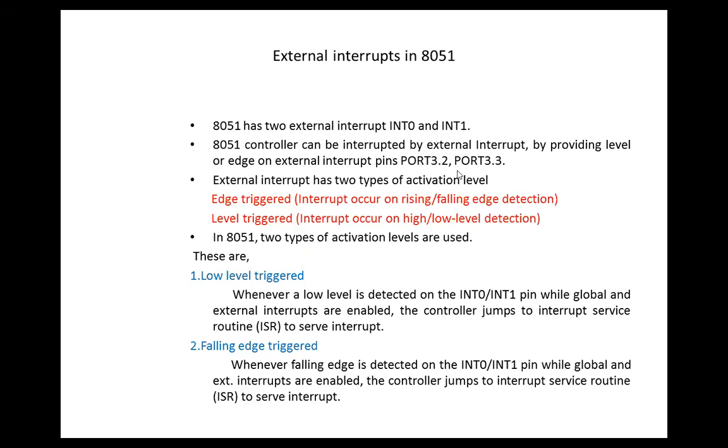External interrupts are, see, we have a... internal interrupts are timer 0 and timer 1. This is not used for an internal interrupt. It is an external interrupt. For that purpose, we have to use two triggering levels, low level trigger and falling edge trigger. See in the diagram how this is.